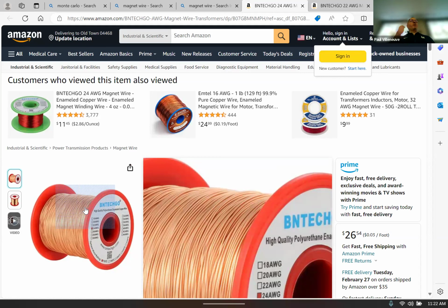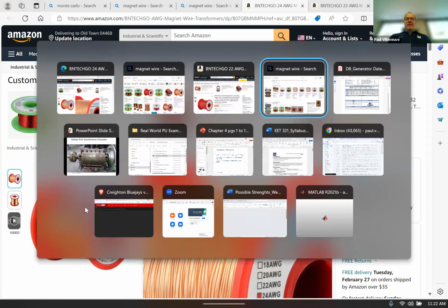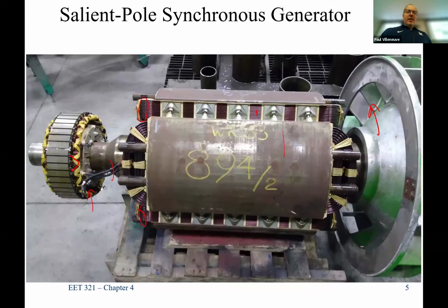And it's just because when they pull it through a solution that bonds the copper, that's where you get the insulation. Because remember, in here, hopefully you can see it, you certainly don't want this copper wire to connect to the adjacent one, because why would it go through the motor? We'd just short out. So you have to have that insulation between there to keep that going.